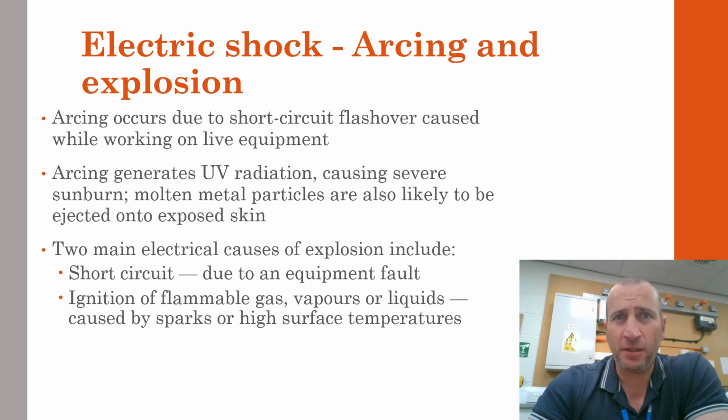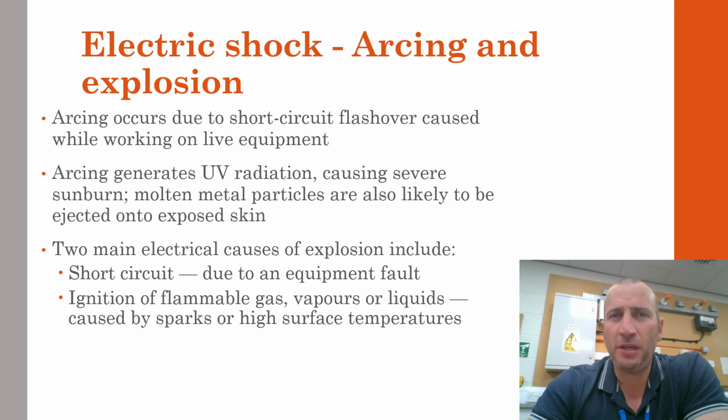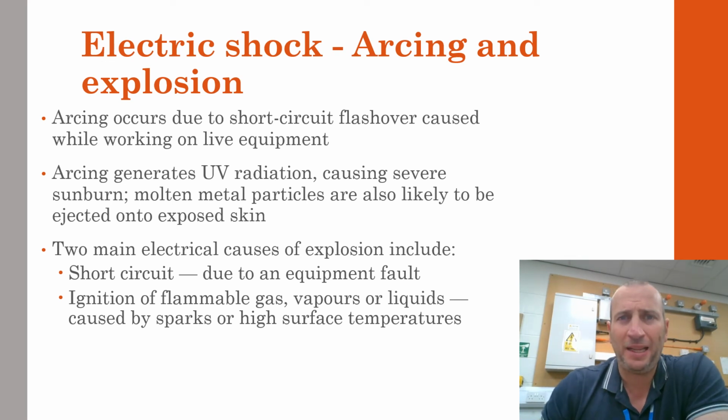In some circumstances, this can cause an explosion due to the ignition of flammable gas, vapours or liquids in the atmosphere. For this reason, some places like petrol stations will have special arrangements for training and tools and equipment that can be used on site. When arcing happens, it can generate extreme heat, burning the contacts. It will generate UV radiation, which can cause severe sunburn, and if enough current flows, the heat will be enough to cause molten metallic particles to fly out onto exposed skin.